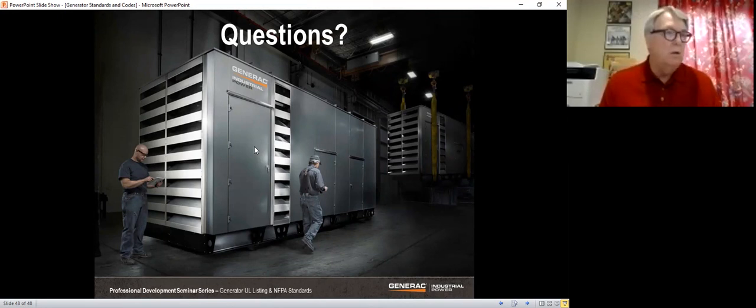It's really not that much. The installer or the startup person's going to have to bring out a load bank, and they're going to have to go through a complete battery of tests and run it for 4 hours, and you're going to have enough fuel to run for 4 hours. There's certainly a cost to that, but in my opinion, it's well worth that cost.